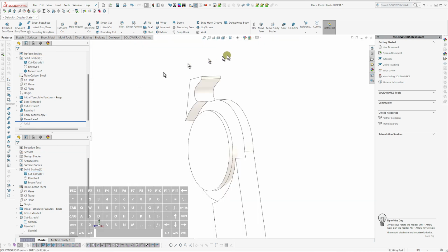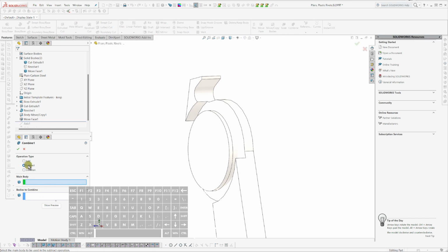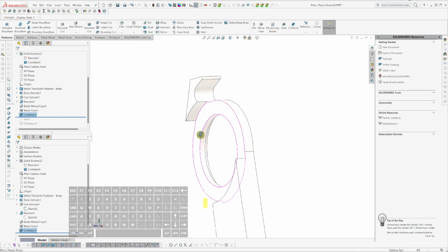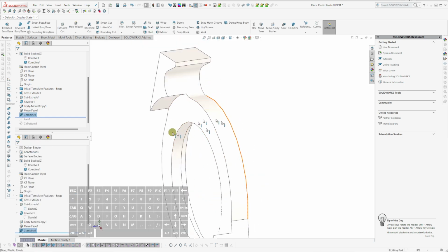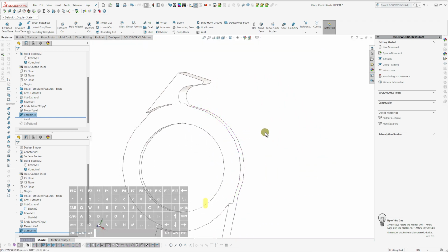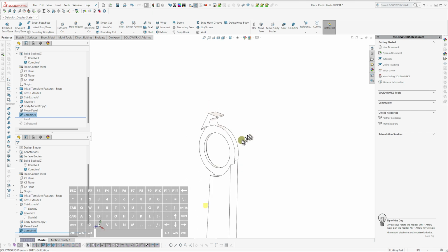And so I will show this guy. And I will combine, subtract style from the main body, a Boolean subtract, basically what it is. This looks a little flimsy, but I think it's fine. For the application, it's just popping out a little plastic rivet. So I think it's going to be plenty strong, especially because I'm going to make it out of nylon, I think.